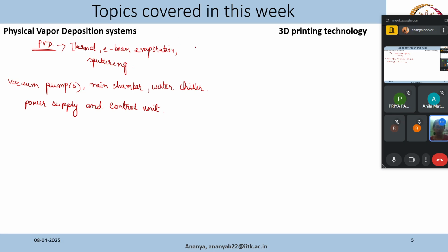So what it will be like is, we will have a crucible, usually of graphite, and we will have our metal here. Okay, and then we will try to put the electron beam at the center of the metal, not on the crucible, because ultimately we want this electron beam to hit the metal or the target material that we are using, and then melt the target material, not the crucible.